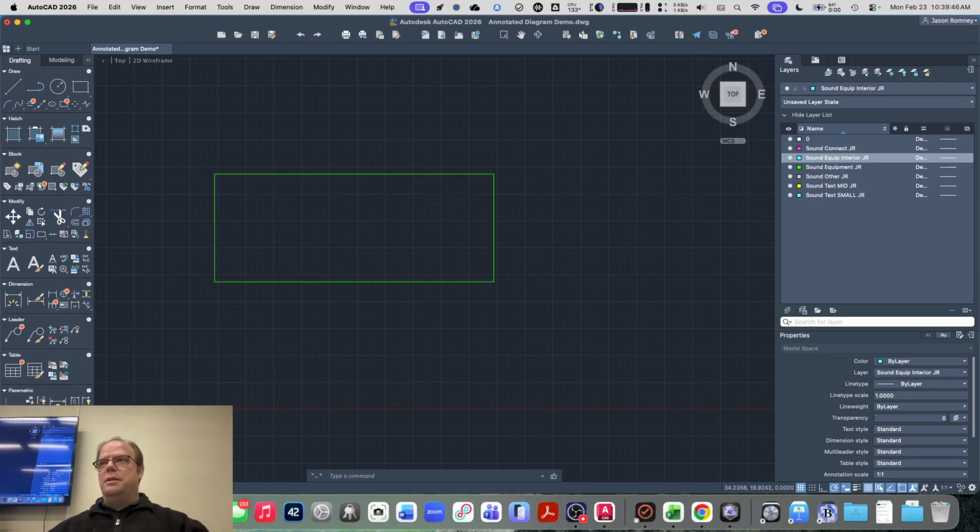You need to see me do that again? Okay. Look at me. I'm going to do L, enter. I'm going to hover over that top corner, and then I'm going to track my mouse down from there and do 2, enter. And it should drop the starting point exactly 2 units down from the corner.